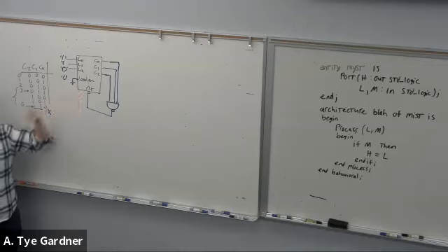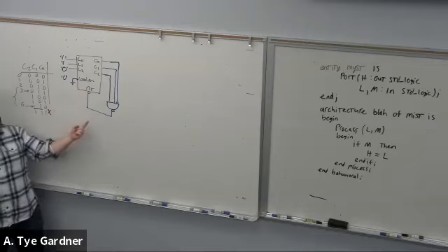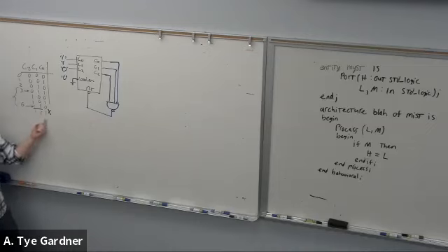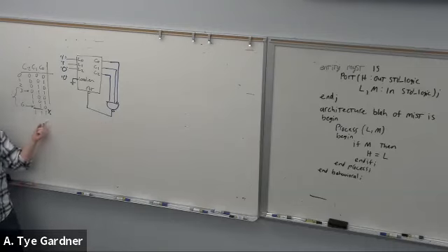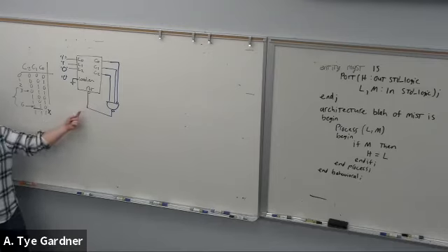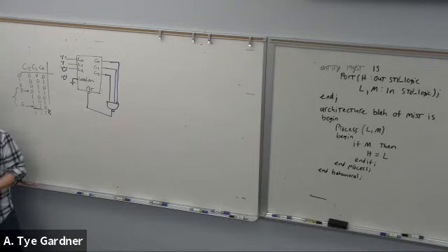So you're not wrong, right? Because if it's an asynchronous reset, I can absolutely do it on 7. The issue is that there will be a brief moment where we do get to 7. But if it is an asynchronous reset, you would have to do it on 7, whereas a synchronous reset is on 6.